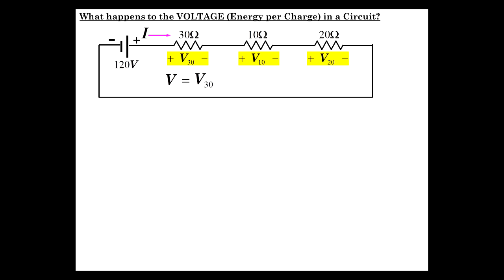Okay. The V, the voltage, for the whole circuit, basically this 120 volts, is the V of the 30 ohm resistor plus the 10 plus the 20. And that's 120 volts. So what is not seen here necessarily, obviously, is that these are drops across each of those resistors, and they equal the rise of the power supply. Now, if you don't know this already, you will from the Ohm's Law lab, which we'll be analyzing next anyway. The circuit resistance, R, is equal to V over I.